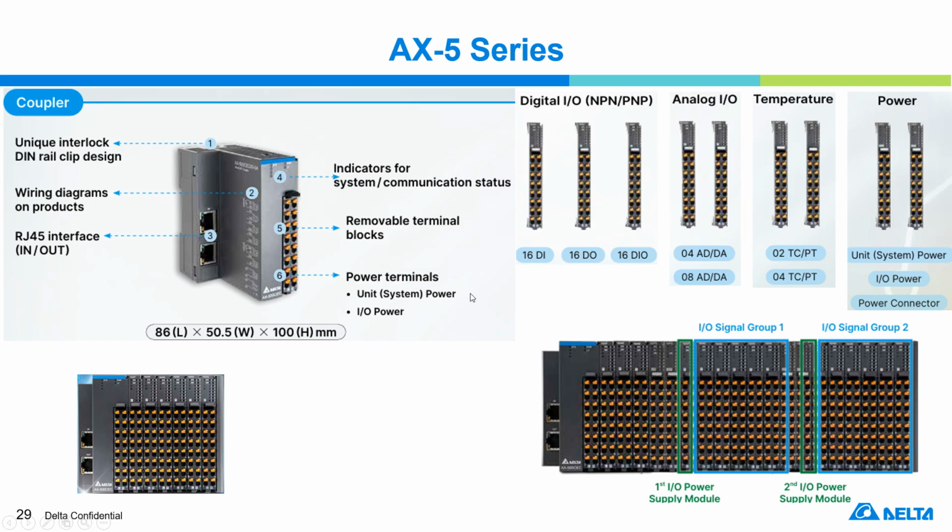Okay, next is the AX-5 series. For this coupler, you cannot find the power terminal on the left side, the top side, or the bottom side. You need to connect the power here, and it can support DIO, AIO, temperature, and the power.